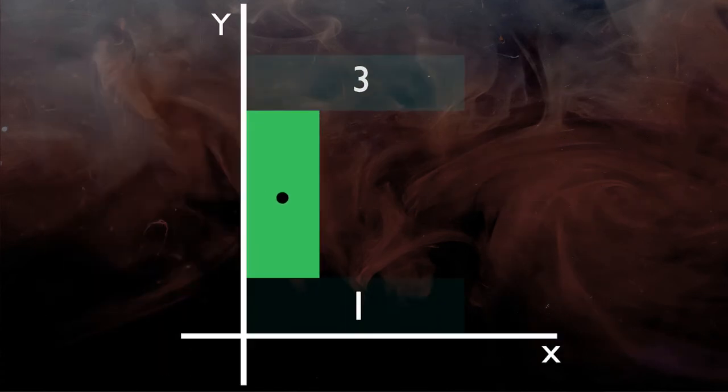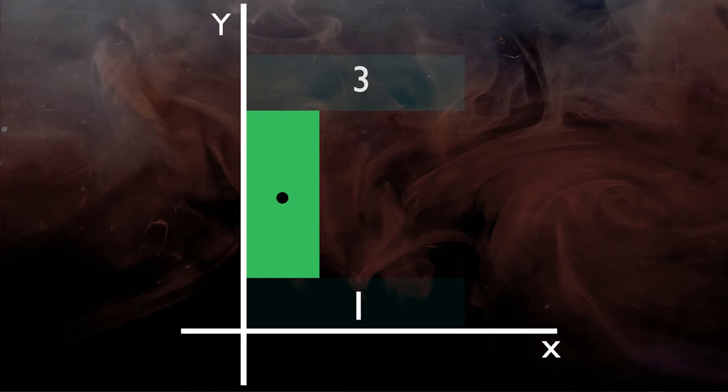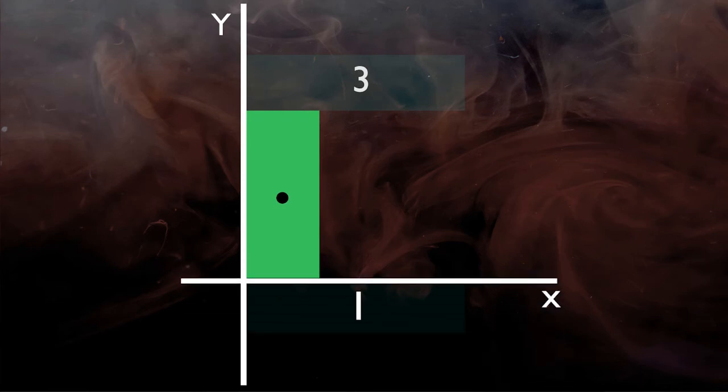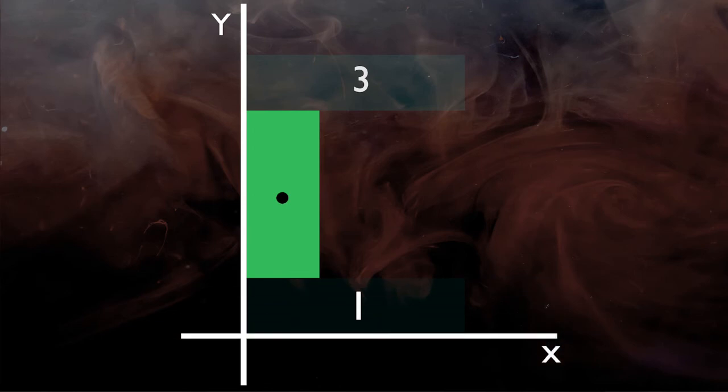But this method can be applied only if the reference axis is placed at this location. But it is not the case. Y-axis is touching the plane of rectangle 2, but the location of x-axis is some distance away. So a little change in coordinates will be necessary. To find the y coordinate, we have to add this distance from the reference axis to the previously found coordinates of the shape.